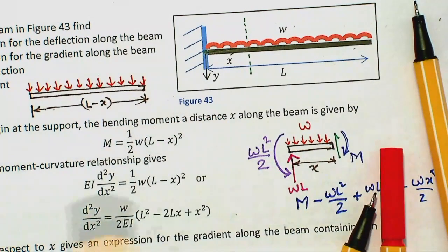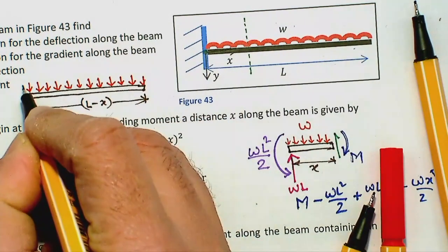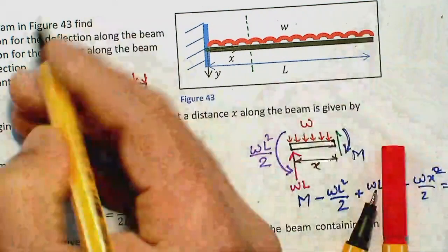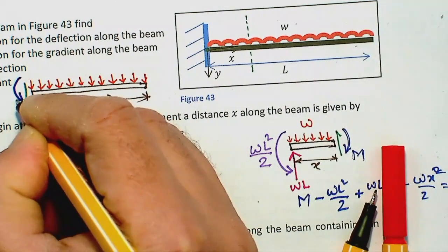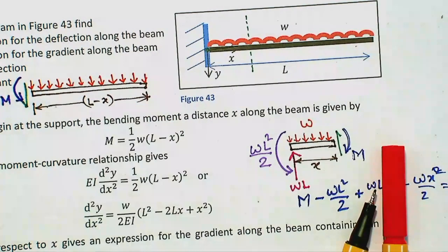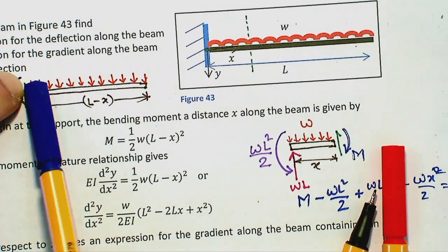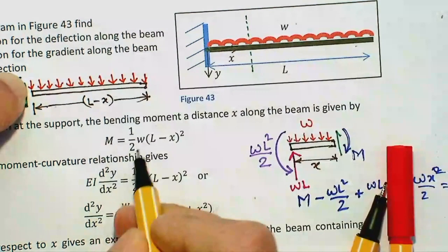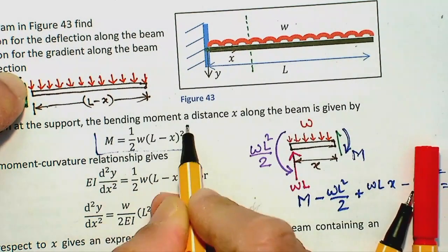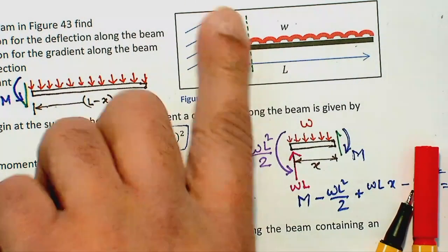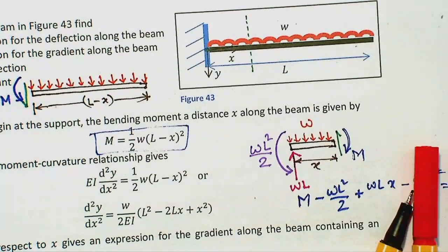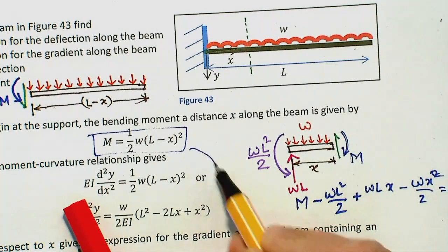Now shear force is, so you have made a cut here, so the shear force would be vertically downward on the left hand side, and moment would be along that direction is the moment. So then moment is W times (L minus x) times (L minus x) over 2. So those are the equations in here. That looks very neat because we got rid of the trouble of calculating the support reaction forces and moments. But these two are exactly similar.